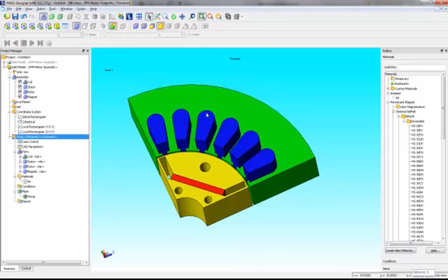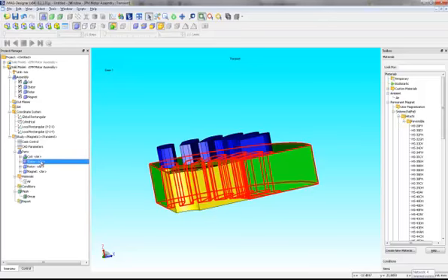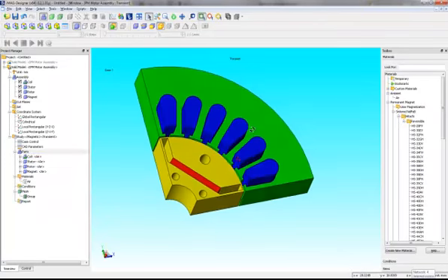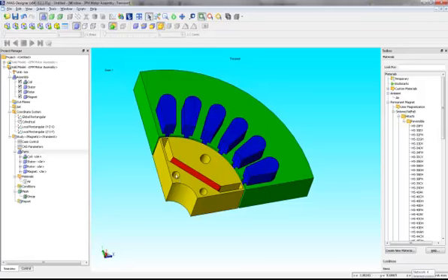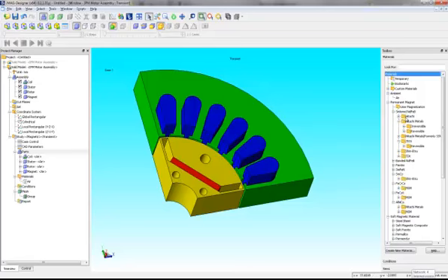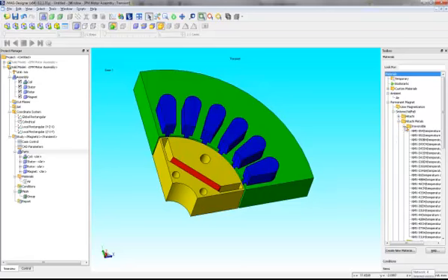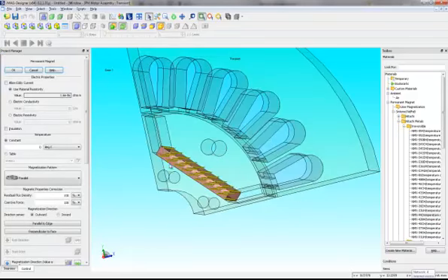Once that model is in JMAG, and this is a model that has no parameter set, it's very easy to create the model settings. So the same as with 2D, we can take our material conditions, and let's put a magnet, a 42 MGOe sintered magnet, or sintered neomagnet. Let's just go with 44. We'll drag that and drop that condition on.